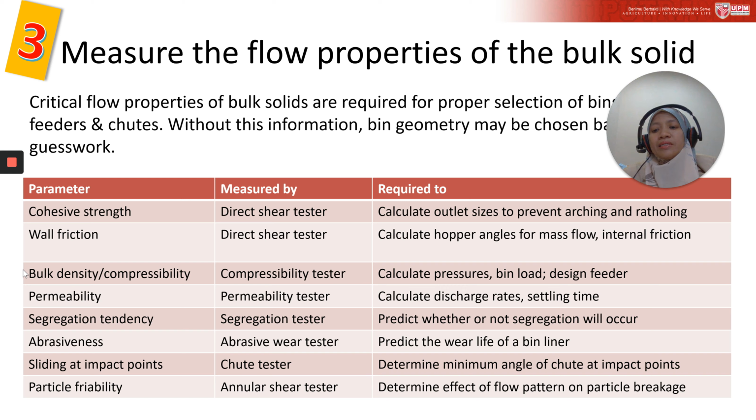Basically, in order for you to simulate, we must understand that powders are very sensitive to the environment. They're very sensitive to moisture. So caking is a common problem in fine powders. So you need to ensure during the testing you simulate the same environment as your process industry, or your process facility.